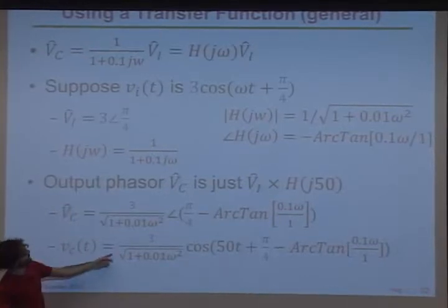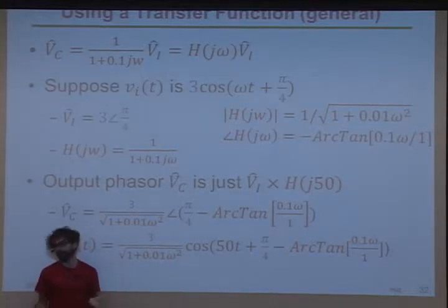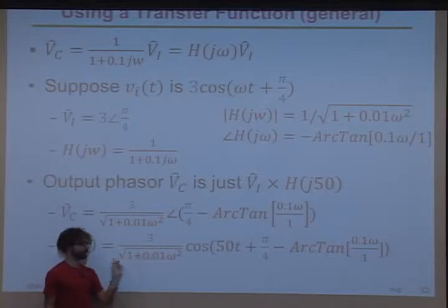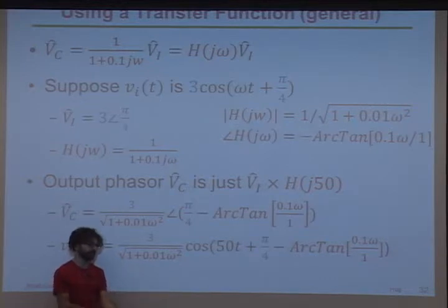So if you'd like, the scaling factor is how much it scales by, this red number. The biggest it can be, because it's a passive filter, is 1. So when omega is 0, it's just locked in where it started. And as omega gets bigger, the cosine is less and less able to show itself at the capacitor, right?